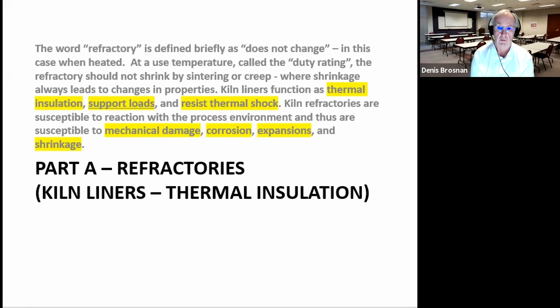It increases the density of the refractory in situ in the wall of the kiln. If that happens, then we've lost some of the insulating ability. We might have opened up joints and have air leaks. So a lot of things can go wrong when refractories shrink.